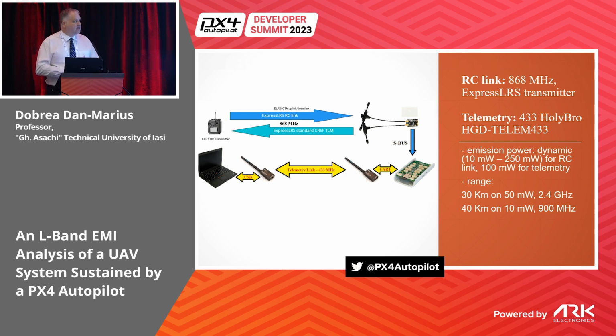ExpressLRS is one of the newest open source standards that is widely used mainly in the FPV world. And mainly I use the main channel of the ExpressLRS, and for the telemetry channel I use a channel based on a 433 megahertz link.